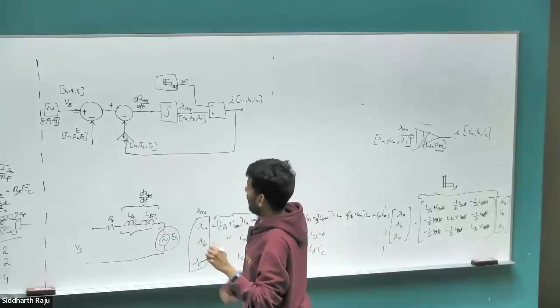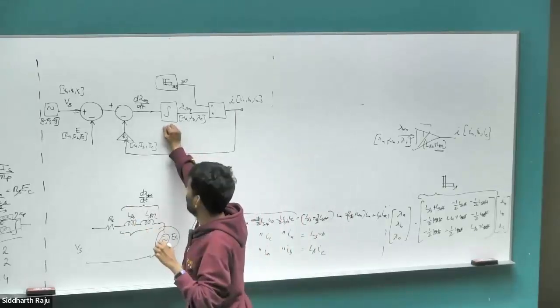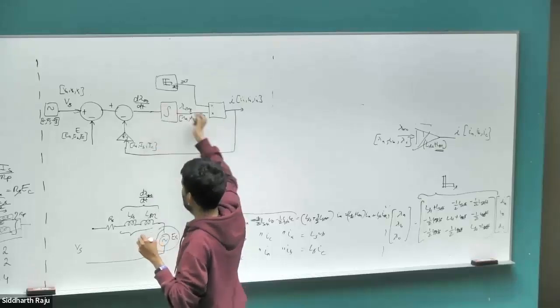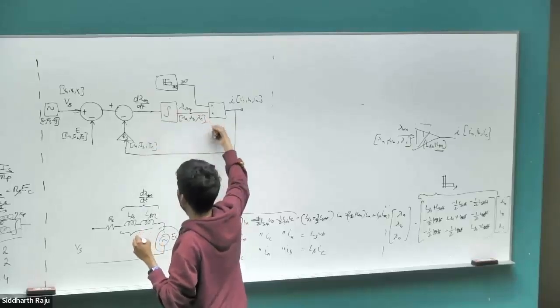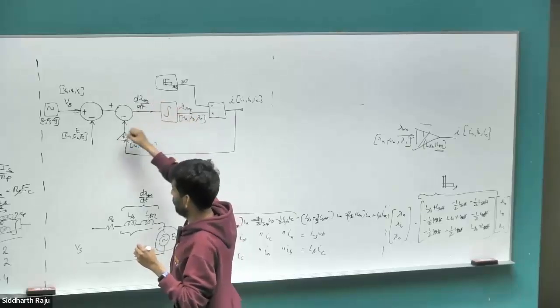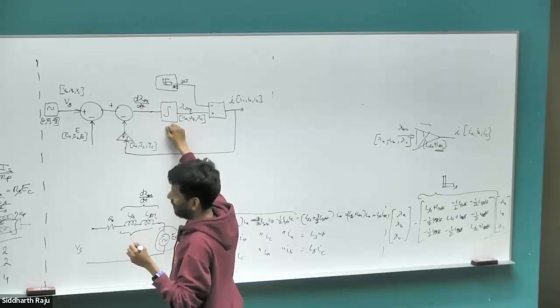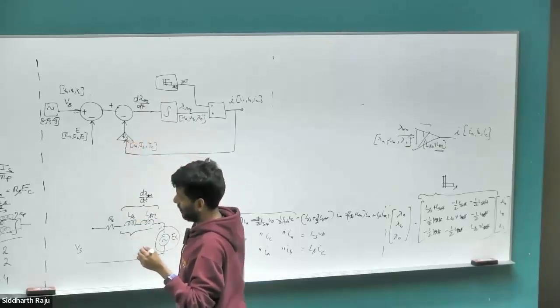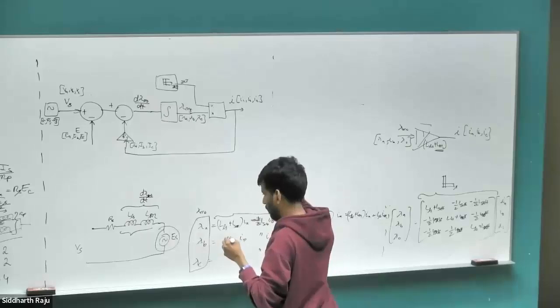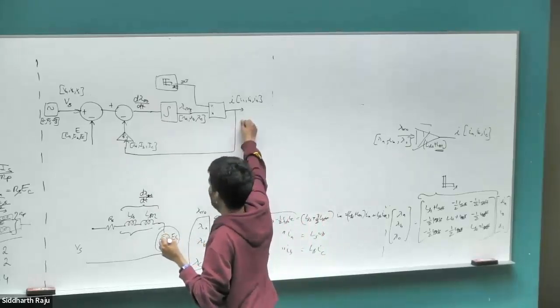Fantastic. Now again, going back, why are we putting it as an integral equation instead of a differential equation? We could have set this equation in such a way that we had lambda, we have the current, and then we differentiated to get your EMF. But numerically, we already saw the stability of integration is much more stable compared to a differential operator. That's the reason we want to go with integral operation when you do numerical simulations. Okay, so we have our currents.